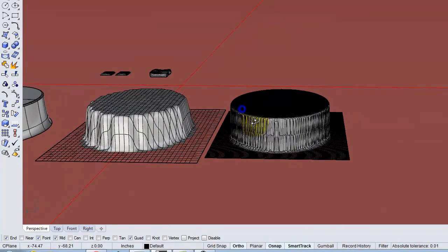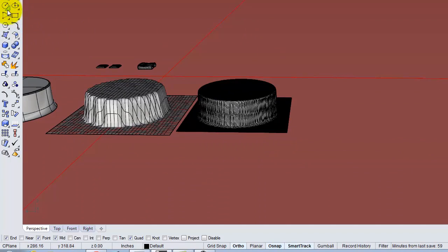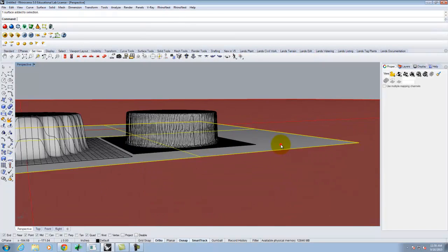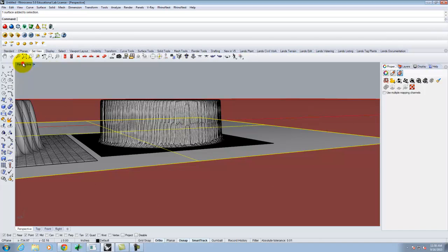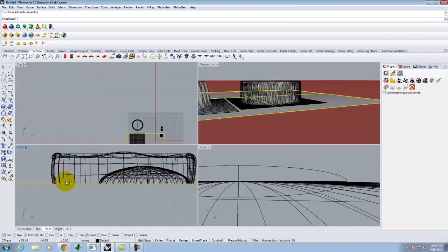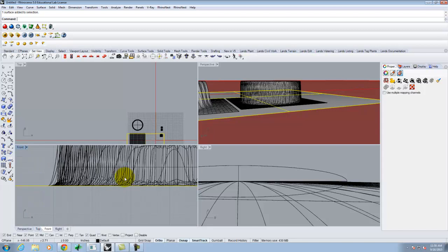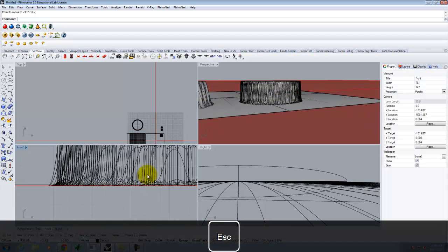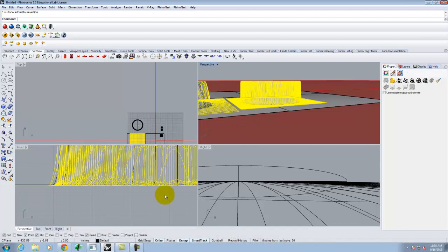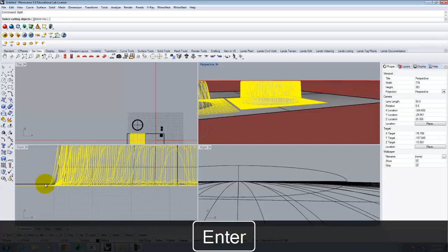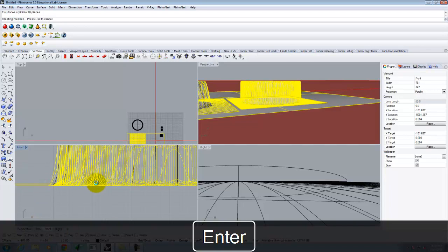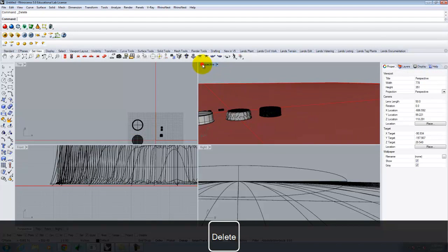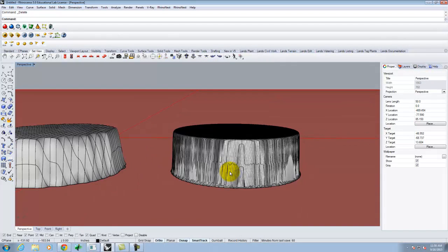Okay? So the last thing is I really don't need the bottom, so I'm going to split off that bottom. Let me create just a standard surface in the XY plane, something like that. I'll use that. We should be able to see it in one of my side views here. There's my table. I need to move it up slightly. Maybe like that. And I need to split these off. So let me take both of those, and I'm going to split them with that surface, which means I can then get rid of the surface and these lower pieces, and I end up with a tablecloth.